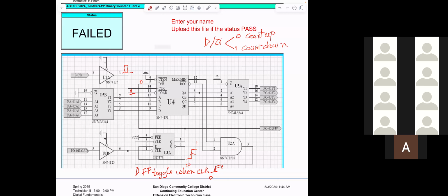When you troubleshoot, you want to measure, for example, pin 9. That means you connect the DMM high to pin 9 on the IC. If you have wiring across the IC, you cannot measure it, you cannot troubleshoot it.